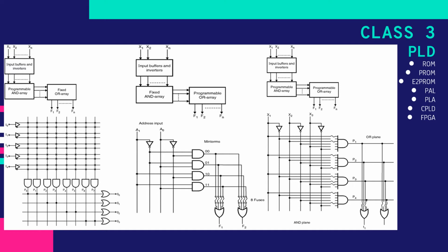PROM will have two basic versions, which are your mask programmable and your field programmable. The mask programmable can be programmed only by the manufacturer and has less delays because they are hardwired. In field programmable, you'll have types like EPROM and E2PROM. They are programmed by the end user. In E2PROM, electrical signals are used to erase the chip.